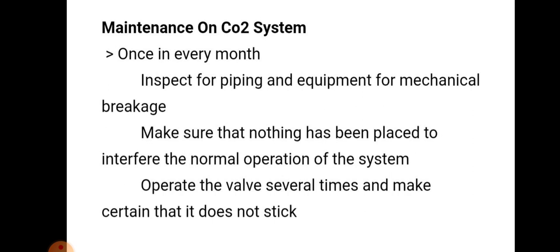Maintenance in the CO2 system. Once in every month, inspect for piping and equipment for mechanical breakage. We have to make sure that nothing has been placed to interfere the normal operation system. Operate the valve several times and make certain that it does not stick.